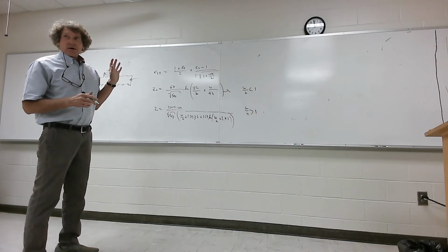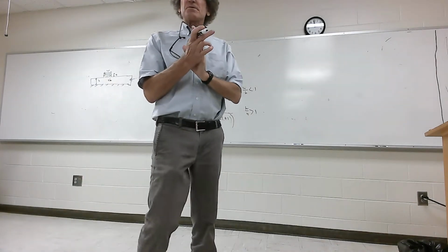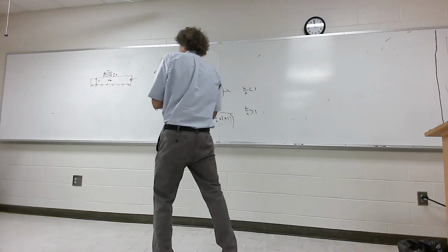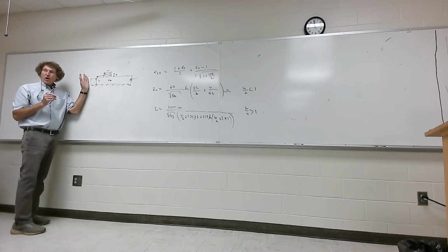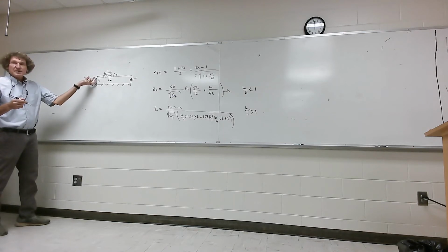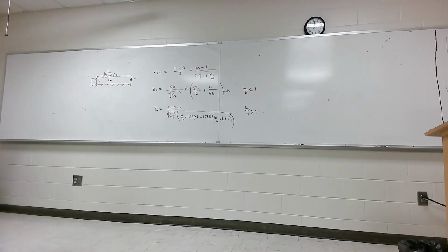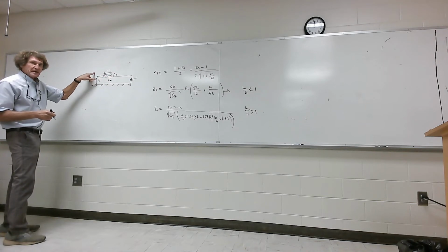I don't have a lot of experience with these formulas, but here's how I got into this. Years ago, I was doing some modeling work for these type of microstrip lines. And here's one of the problems. When this right here gets close to the edge, all of a sudden the characteristic impedance starts changing. And a lot of times you want to get something near that edge because you want to make the best use of the space. It's called the footprint that you have to work with. It's really the amount of board. They want to put every device you can on there, and you want the smallest possible size. But these formulas work only when you're in the center of the board. As you get close to the edge, things change.